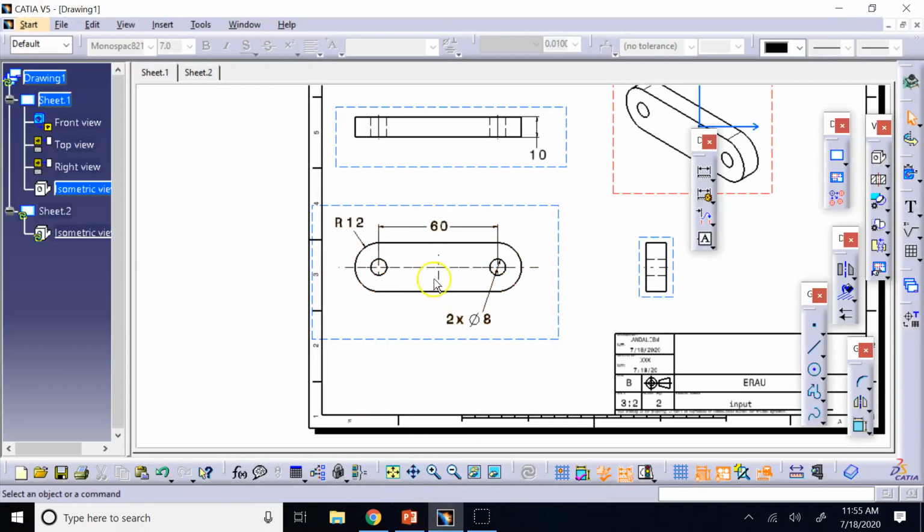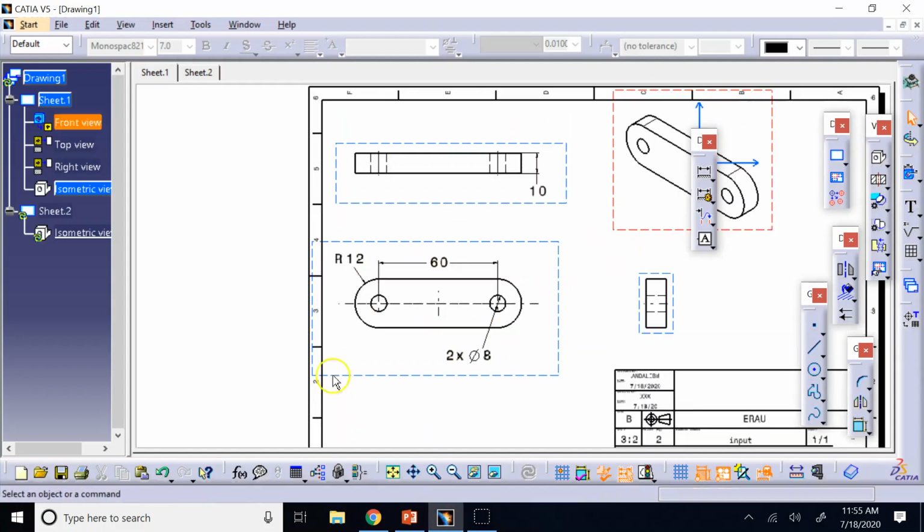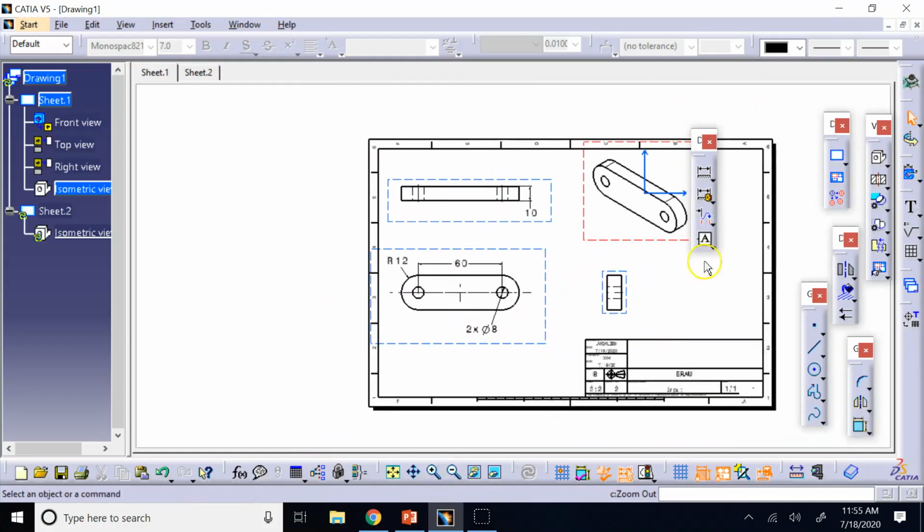Again, in this case, since the part is symmetric, it's not mandatory to add that. So now, is there anything else I need to add to this drafting? I had a major part, I provided the width, the height, and the depth. I have provided the diameter of the circles. I have provided the location of them with respect to the center. And that's all this part has. It's not a complicated part. And I provided, of course, the radius of each arc.